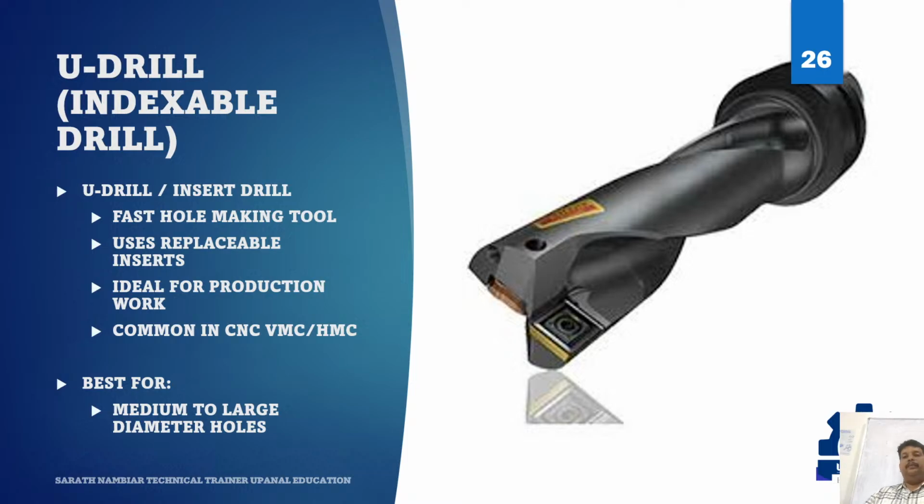Next is a U drill. This tool is also called an insert drill or indexable drill. Unlike normal twist drills, U drills use replaceable inserts at the cutting tip. Why is that useful? When inserts wear out, many times you replace the insert instead of replacing the whole tool body. This can reduce the cost in a production environment.